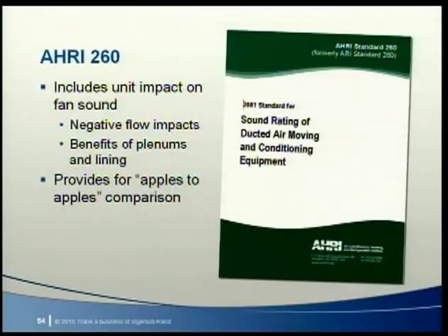There are two developments that have greatly improved your ability to choose a fan with the best acoustics for your application. The first is ASHRAE 260 Sound Test Standard for ducted air moving equipment. This standard accurately accounts for how sound for a given fan changes with flow, pressure, and size. It also accounts for all unit-based sound changes, including flow disturbances and cabinet effects. That means you know exactly how much sound is leaving the unit.